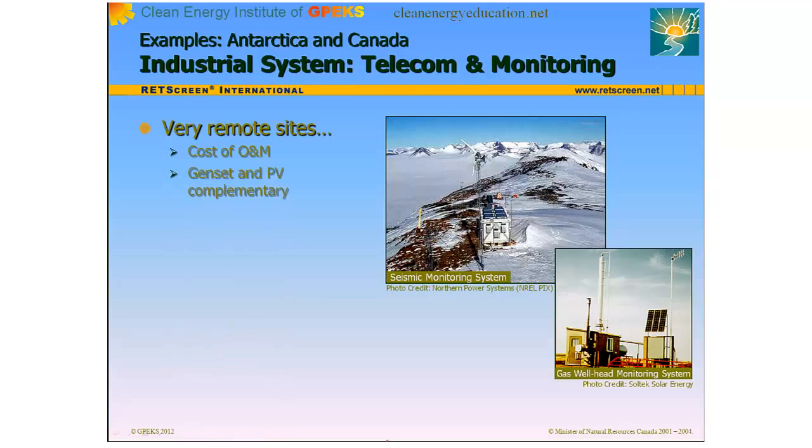In general, the characteristics of gensets are the opposite of those of photovoltaics, and this makes them complementary power sources. Gensets have low capital costs but high operation and maintenance costs. By combining the two in the same system, a smaller PV array can be used, curbing capital costs, at the same time that fuel consumption is decreased, lightening the burden of O&M.